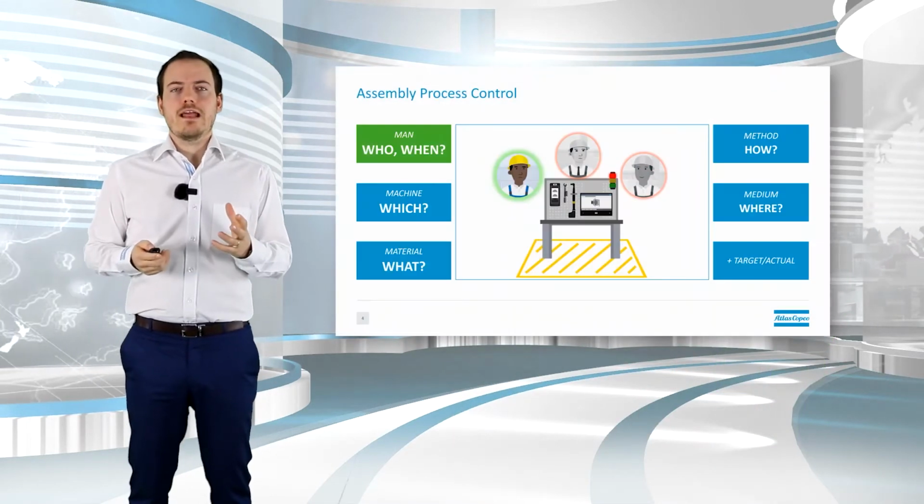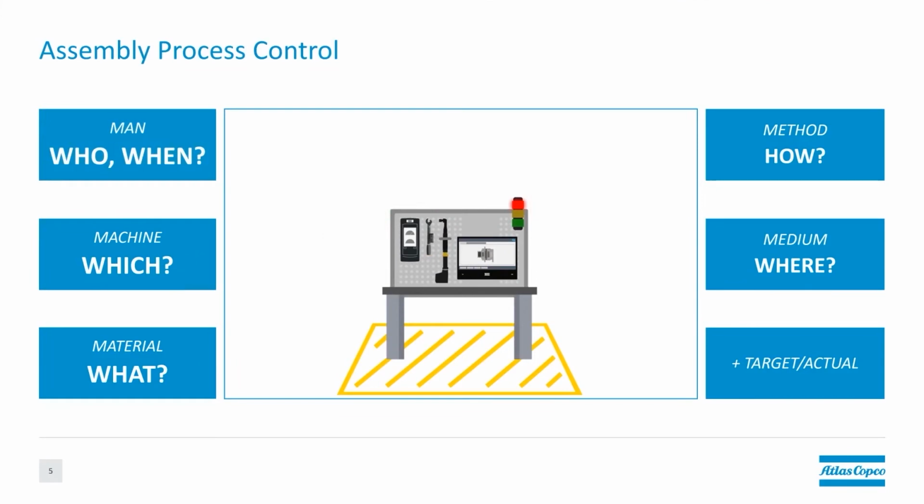Let's continue now with the analysis. The machine. Which machine are we using? What you see here in the image could be three tools. Maybe you say those tools are not similar, so how can they get confused? Maybe not a battery tool with a click wrench. But what happens if it's in a repair station and they have all click wrenches? They are all quite the same. Couldn't they be choosing the wrong one? Could it be that, if there are different tools, they are selecting the wrong parameter? Could it be the wrong batch count for that one? Maybe.